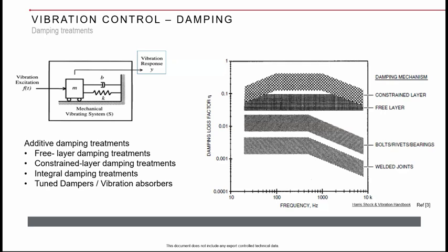But one criterion is, if you want to understand whether the damping present in your system is viscous or structural damping, you can try to plot a Nyquist plot with mobility.